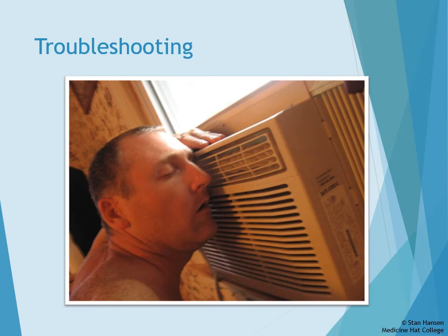If you do not have voltage at the power relay, then step backward from there, working your way back towards the thermostat. Check the outdoor switch. If the outdoor switch is open, you should have 24 volts between the common and the input side of that switch. However, you will not have anything coming out of it. And that would indicate that if it's too cold outside, that switch is likely to be open. However, if it is warm outside, that switch needs to be changed.